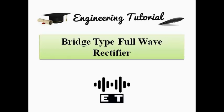Now in my previous video I discussed the center tap type full wave rectifier. We discussed the circuit diagram of the full wave rectifier, the circuit behavior during the positive and negative half cycles, and the disadvantage of the center tap type full wave rectifier. The disadvantage which we identified was that it was very difficult to locate the center tap point in the secondary winding.